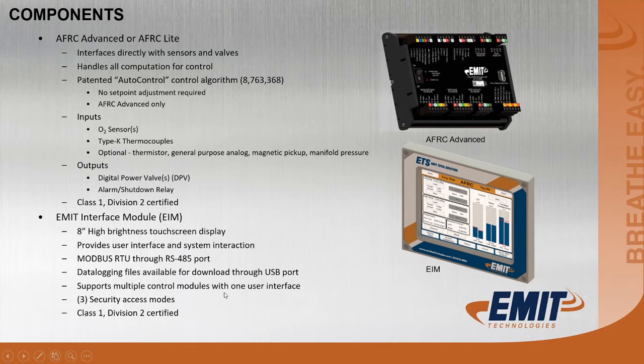It supports multiple control modules with one user interface. By that it means we can run an AFR, a governor, an annunciator, and ignition. All of those can be tied together at the same time using one module, or any one of those modules can be used with this display independently. It has 3 different security access modes. In operator mode, you can't make any changes, you can only view. Then there's a mode for setup, and a mode for engineering. And again, this one is Class 1 Div 2 certified.